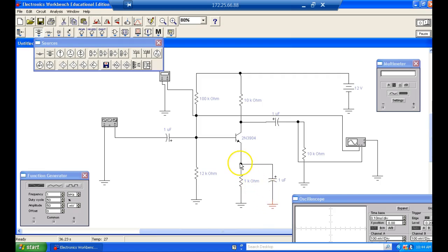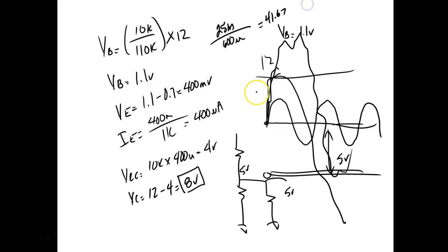Right. So this is going to be 5K divided by 44K. Nope, something's still not right. No, that's my input impedance. So it's going to be 5K divided by 44 ohms. So what would our gain be? So I had the input impedance formula on my mind. So the gain we should expect now would be 5K, which is our output resistance, over RE prime.